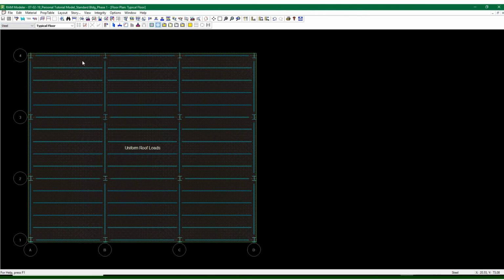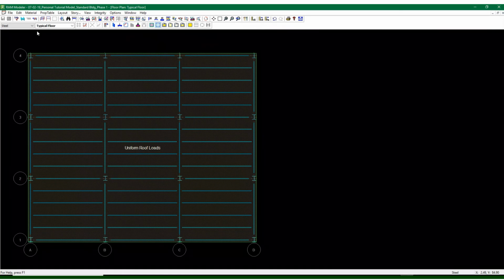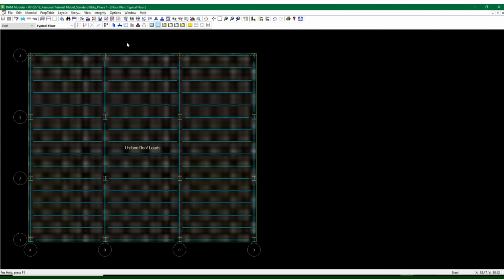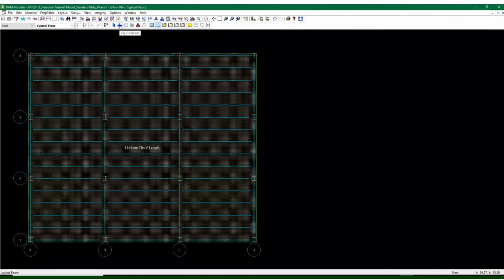Say okay. Now I have a total load of 55 PSF on this, plus the self weight of the deck load on this and the beams, the structure, et cetera. Now I can hit the escape key and nothing happens, but I want to reset this because this is just showing me my hatch load area, and I want to now find out some information about the beams themselves, particularly their boundary conditions, their fixities at the columns.